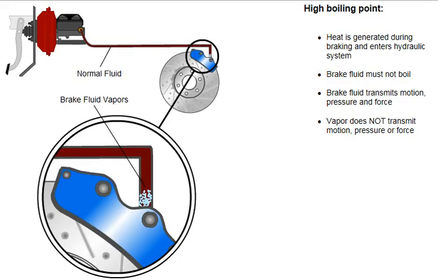A great deal of heat is generated during the braking operation. This heat enters the hydraulic system. Brake fluid must not boil and transform into vapor, because vapor does not transmit motion and pressure or force the way liquid does. If the brake fluid boils and turns into a vapor, the brake system will fail. Therefore, brake fluids must have a high boiling point.